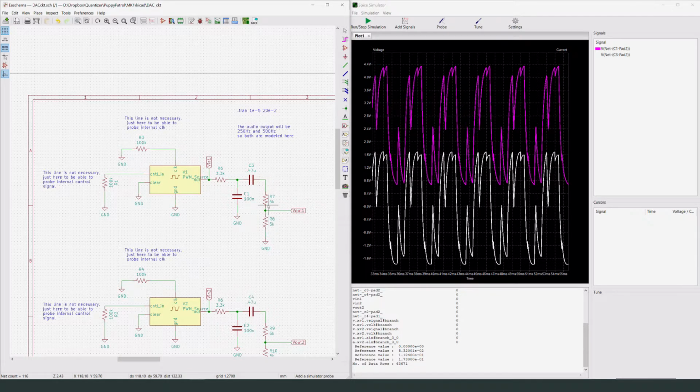So right here, this is simulating the potentiometer that we put in there, which is just a resistor. You can vary what the middle output's resistance is at, whether you have it all the way up at the input, somewhere in the middle, or all the way down at ground, which would be 0 volts, right? So this one's right at the middle between 5K and 5K because it's a 10 kilo ohm potentiometer that we're using. And so you'll see here that this should be half what the input is, and that's what you got. Same wave, just half, and that's how we're going to control the volume with it.